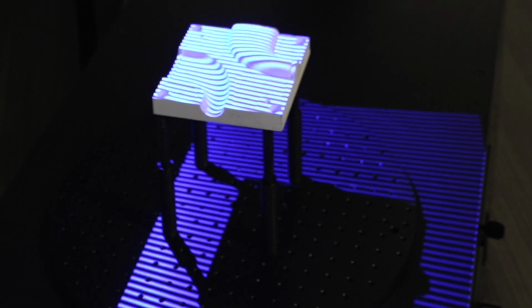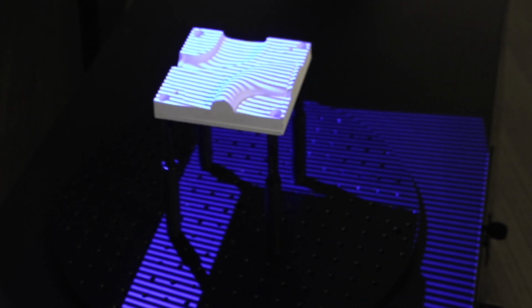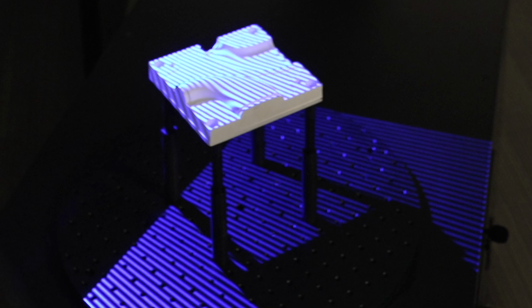Now that that scan is complete, we can simply put our next part on the scanner rotary plate. In this case, it would be Mold 2. We can go over to the scanner software since we already have PolyWorks set up and connected to our scanner software. We can simply click on Execute Automation. It'll run through the program, scan the part, export out the data to PolyWorks. PolyWorks will grab it, pull it into the inspection report template that we had set up, extract all the measured values, and output the inspection report to the inspection directory.